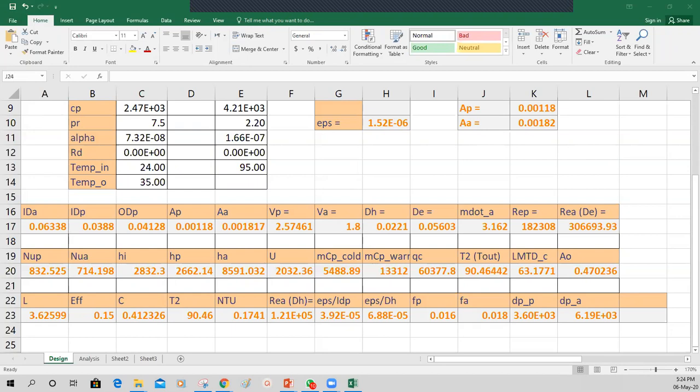And that 5 kilowatt you are equating, making it equal to m, the size of the boiler, multiplied by Cp and multiplied by dT, and divided by the time also, 5 hours or whatever. So anything unknown can be found from here.